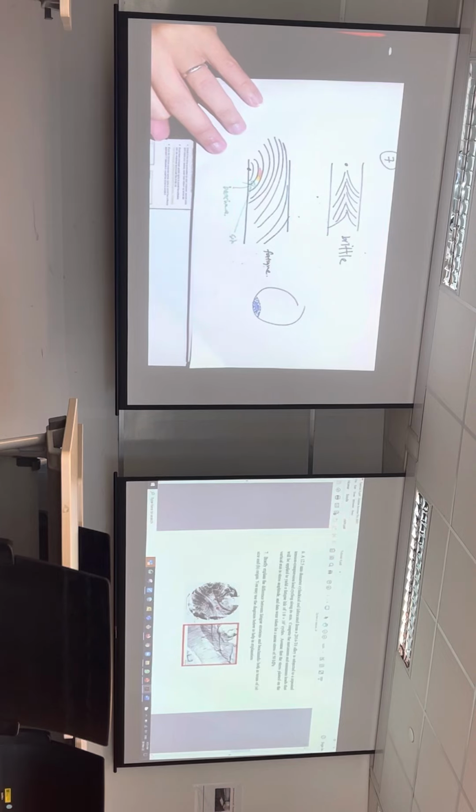So it's not a time zero failure, because it's still within your overall use stress limit. But every time the crack opens, the part is more and more likely to fail because the eventual load bearing area is getting lesser and lesser. So this is the difference.